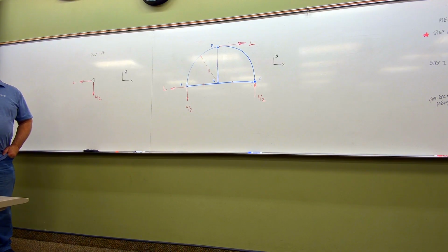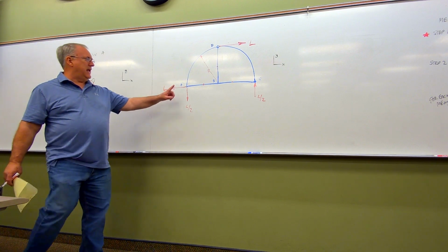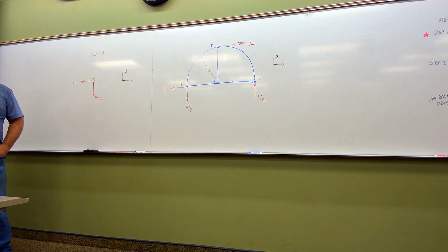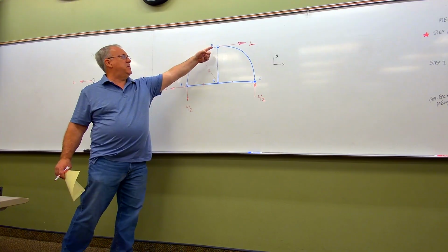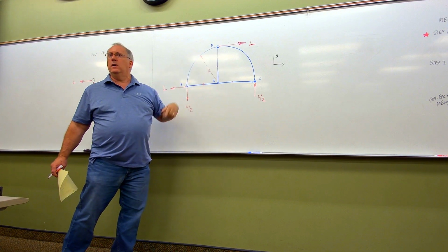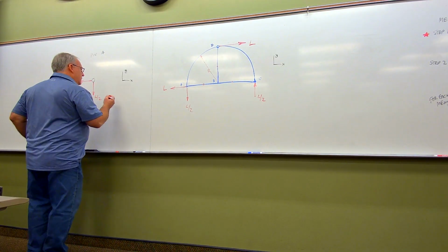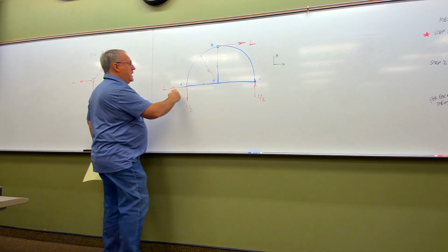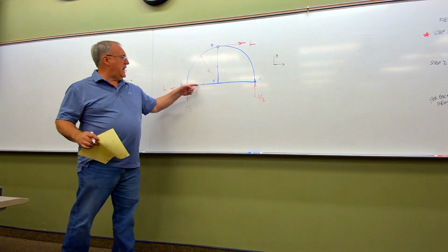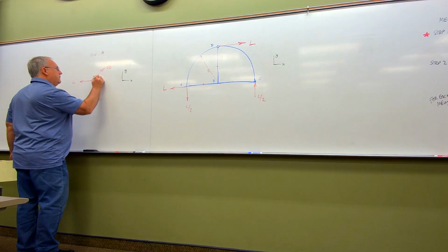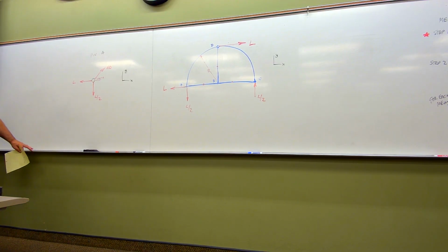Now, I will say that it is not unusual. When you look at this at first, you might think, well, man, I need to come up with some sort of a tangent line right here or something like that. It's a common mistake, but it's exactly what it is. It's a mistake. Here's where we have to remember one more time. We couldn't care less what the shape of a 2-force member is. All we care about is that the force in a 2-force member is drawn on a line that passes through the pinholes. So in this case here, the force that is in member AD is going up like this, because again, we're on this line passing through these 2 pinholes, and because that distance and that distance are the same, their radiuses, that means this angle right here has got to be 45 degrees. So look at that, folks, just like that. Very fast, very simple free body diagram.